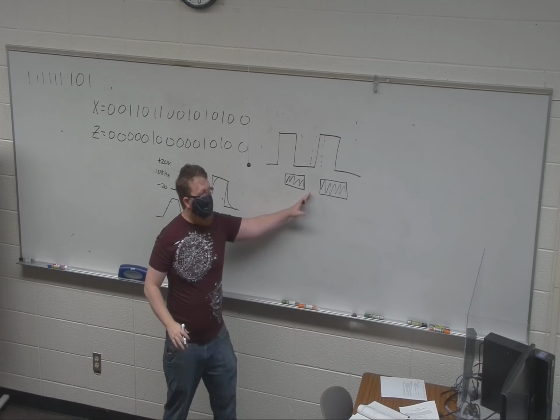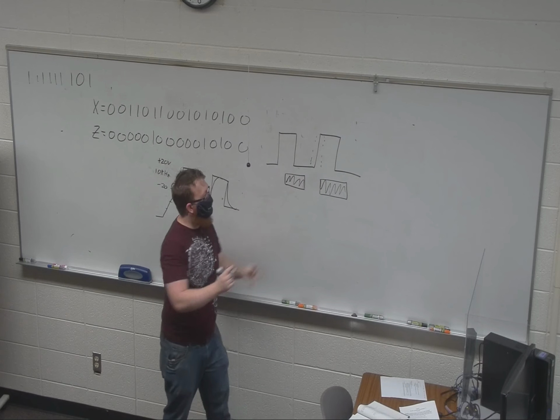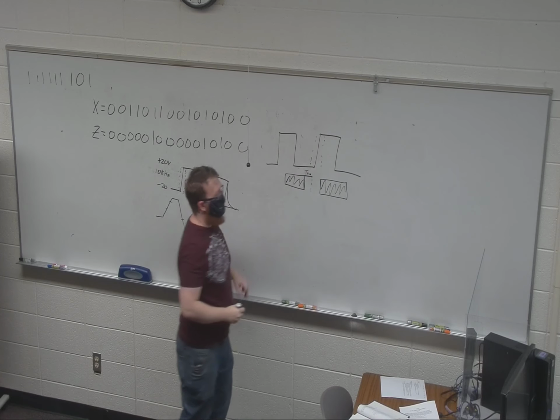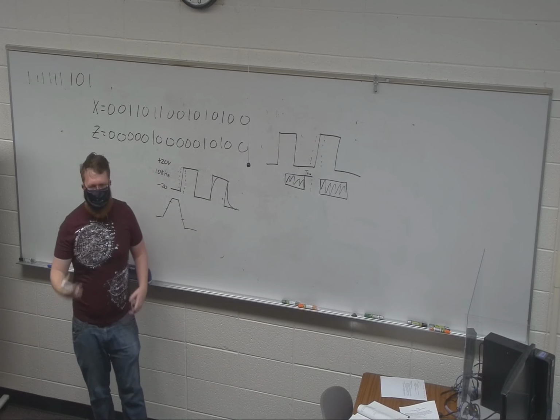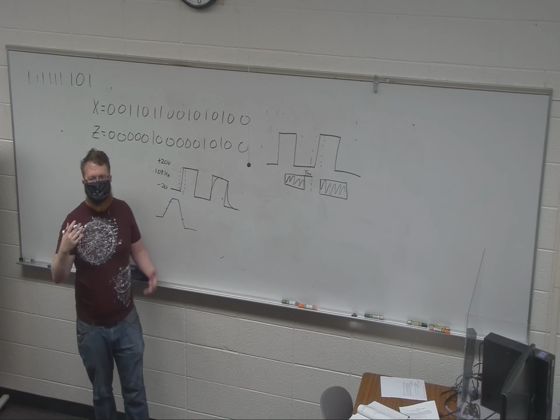But before you change the data, to make sure that the clock jumping around doesn't hurt you, you need to have something called setup time, TSU. That's saying set up your data before the clock has any chance of happening. So you're going to see these specifications on flip-flops to set up your data to be ready to read it.